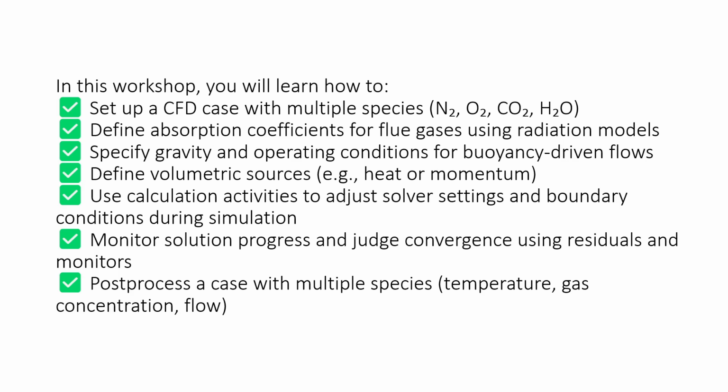Alright. Now let's talk about what you'll actually learn in this workshop. This session is packed with practical, hands-on skills you can apply to real-world simulations involving fire, combustion, and buoyancy-driven flows. Here's what we'll cover: how to set up a CFD case with multiple species, like nitrogen and oxygen, to realistically simulate fire and combustion gases. How to define absorption coefficients for flue gases using radiation models, a critical step when dealing with high-temperature environments and radiative heat transfer.